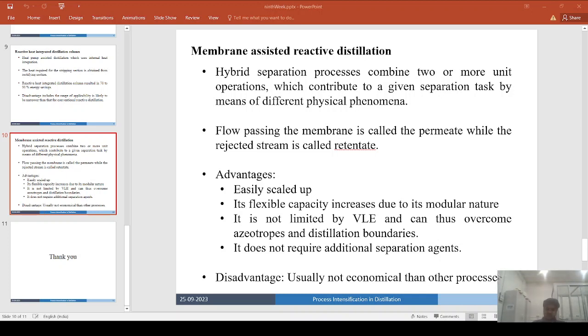In terms of application, there is the use of pervaporation to break the low boiling methanol methyl acetate azeotrope during the transesterification of methyl acetate with butanol. It is a paper by Steinweg and Melling in 2004. Another paper by von Scala and others in 2005 showed that this integrated process has also been applied to the production of cosmetic fatty acid esters, utilizing the principles of MARD.